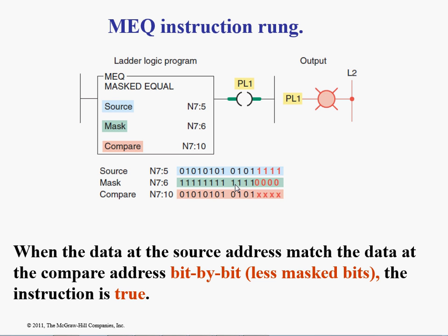And say that that's the condition. That would probably be an easier thing to do, to say that all this stuff has to be shifted this way in order to run, than to do this instruction. Personally, I've never used it. If I was going to do something like that, I would use normally open, normally closed instructions in a certain sequence to turn on a bit saying that you've got it set up for product A and it's okay to run. That makes sense?